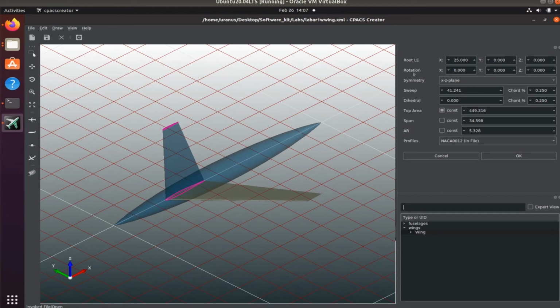The rotation around the x, y, z axes you can also define, especially if the wing is rotated around the y-axis. We usually say this wing is twisted. It is quite common that the aircraft main wing section is twisted along the y-axis. A vertical tail, for example, is a non-symmetric wing rotated 90 degrees around the x-axis.